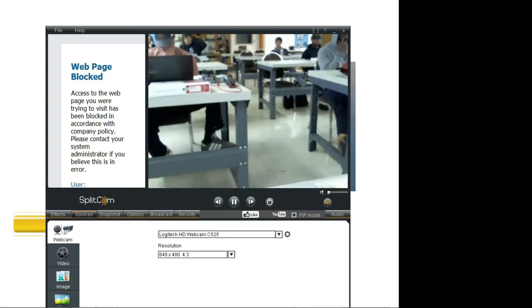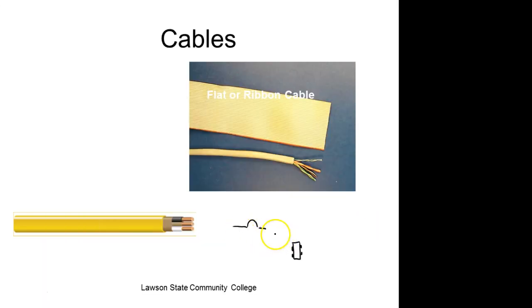So normally what most electricians do, it's the fast way to do it, is they'll bring this black wire in there. And then they'll take this off here, off this screw, and send it on down to the next plug. And then you'll bring your neutral in. It'll go to this. Then they'll tap off this other screw and send it down to the next plug. And then the next plug will do all the same thing.